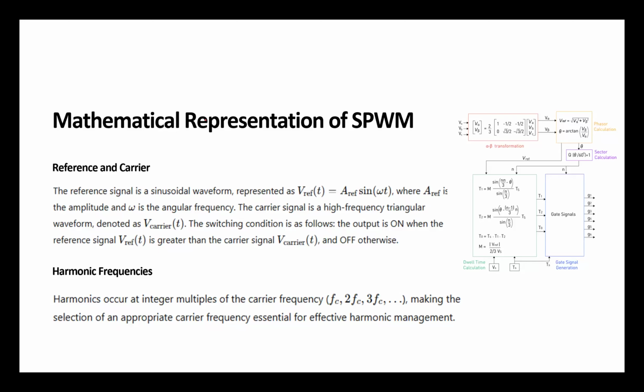The microprocessor can optimize the switching to reduce the harmonics that exist and ignite the switches based on the new PWM. This is what's happening in industrial scale inverters, but it's too expensive. So in cheap, household scale inverters, they don't do that. They just use a simple analog oscillator for the PWM. Did I answer your question?